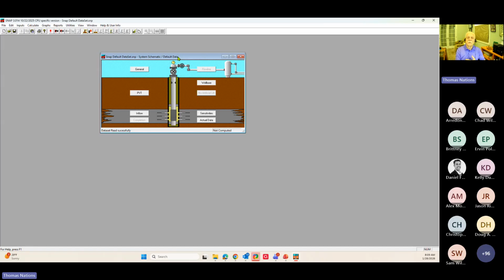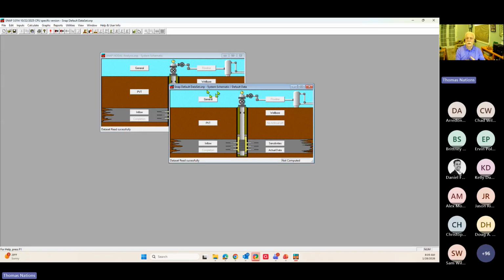And then to confirm that you have a working version, when you have this default data set open, do the calculation run, and there are 3 different ways to do that. Let me explain that to you. So you can calculate all, or you can push this red exclamation point. That's a calculate all, or depending on what kind of keyboard you have, it's F5 on your keyboard.